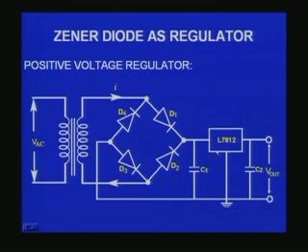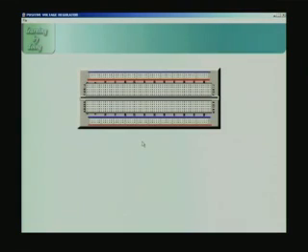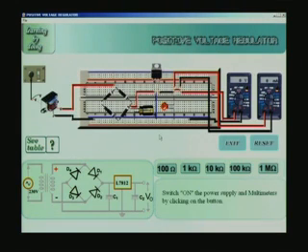One can also make a negative power supply. But before I go to that, maybe I will just show you the actual circuit of a positive voltage regulator. You can see this is the positive voltage regulator in TO-220 package. That is a transistor outline package that you have here. It is an IC regulator, as I mentioned to you, not a transistor. It has got 3 leads. One is the input, the other is the ground, and the third one is the output.